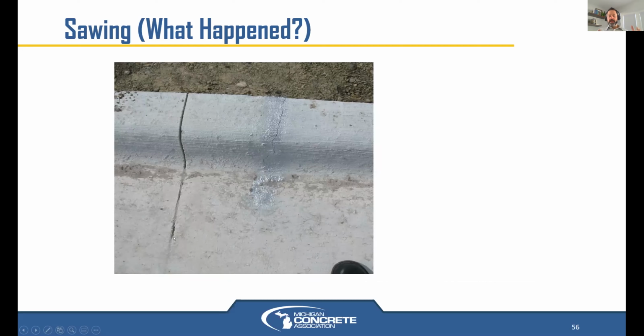However, a standard saw or even those soft cut saws can't climb up the vertical face of that curb and on the top of that curb to cut that. So it's a second step operation to finish that saw cut, and it's typically a handheld cutoff saw. So that second step was not placed in time. You'd need another crew member with that cutoff saw walking right behind the walk behind saws and those operators to finish those cuts and not rely on that same operator to stop, drop back with that other tool and finish that cut.